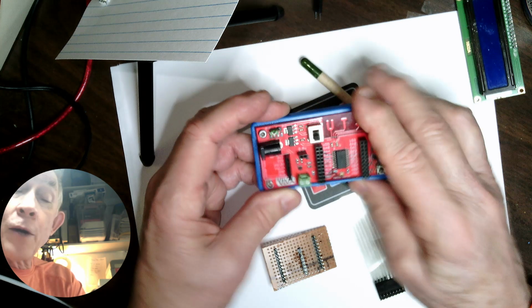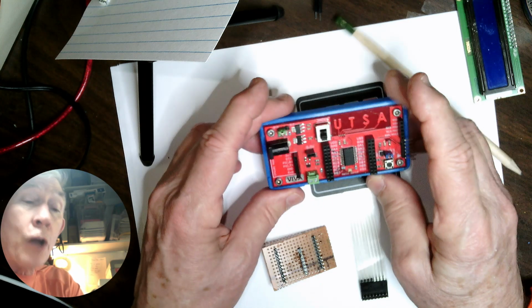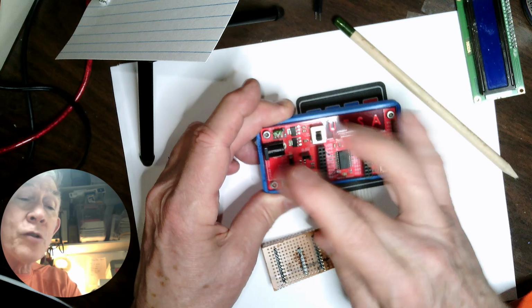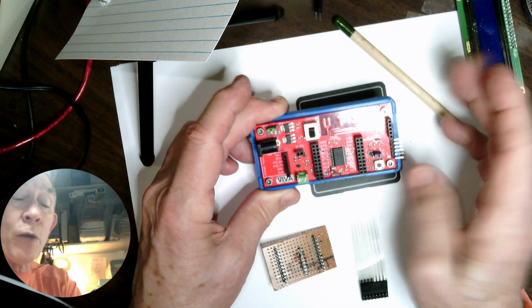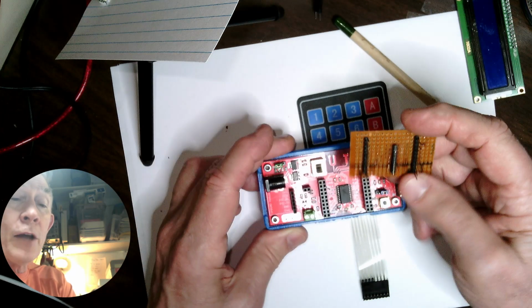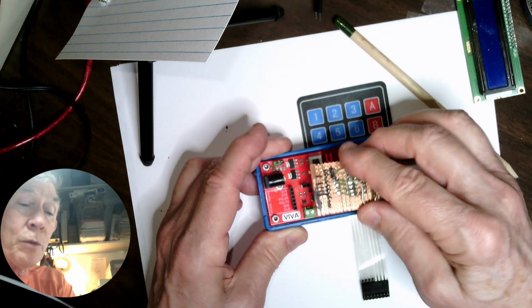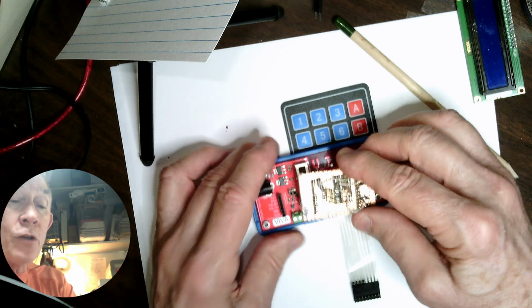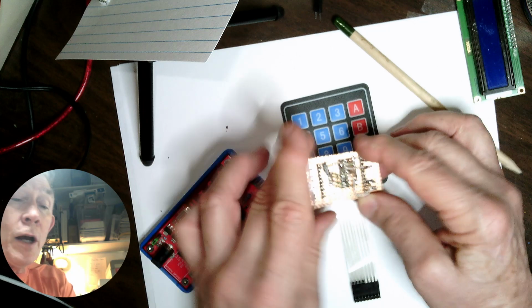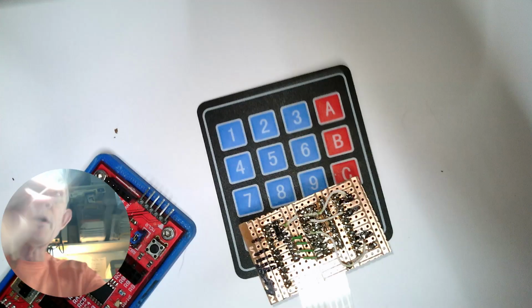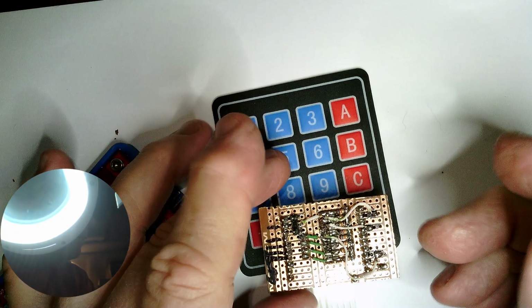And when we laid this board out, we laid it out on a grid that was 0.1 center. So I know that all my pins on here are spaced at 0.1 spacing. And since this board is laid out in 0.1 spacing, I could set this up so I knew it would plug in once I kind of lined everything up. And so I plug it in. Notice also here, let's see if I can bring this closer and get a nice close-up. We'll see. I don't know if I'll be able to do that or not.